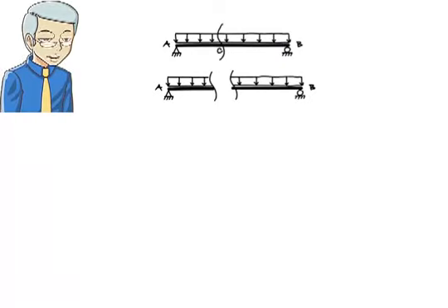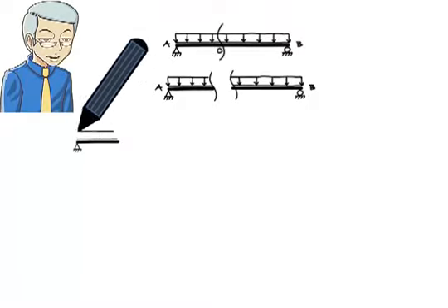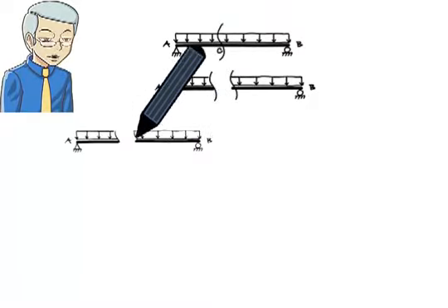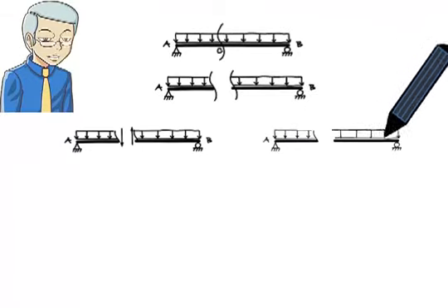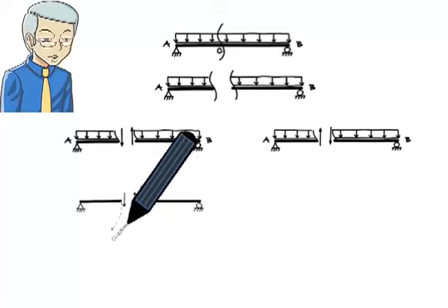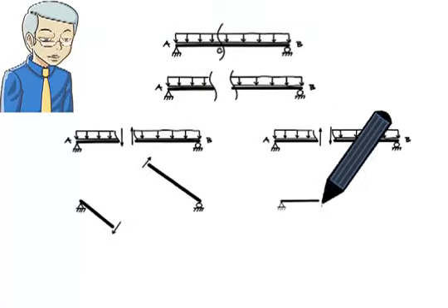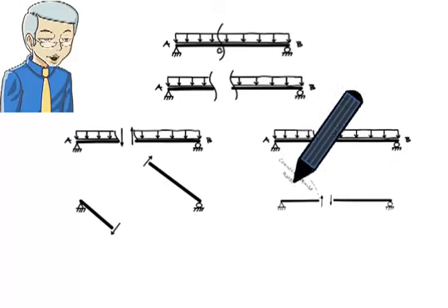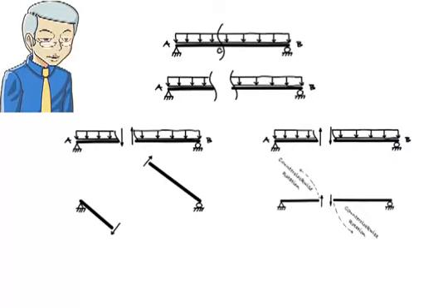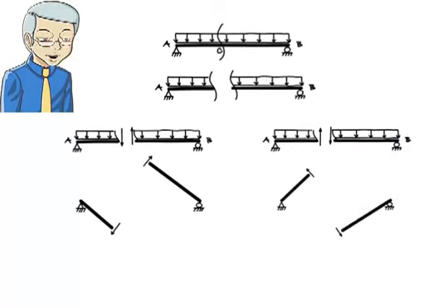The shear force has to be shown as a pair of vertical forces acting in opposite directions, so the pair has to be drawn either like this or like this. In the first scenario, the shear force tends to rotate the beam segments in the clockwise direction. In the second scenario, the rotation of the beam segments tends to be in the counterclockwise direction.